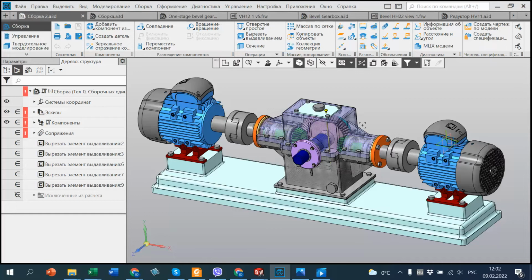That's why it's gear reducer. Another name, reducer, because sometimes it may be multiplier, which increase rotational speed. But in our case, input rotational speed is higher than output rotational speed. So that's why it's a gear reducer.